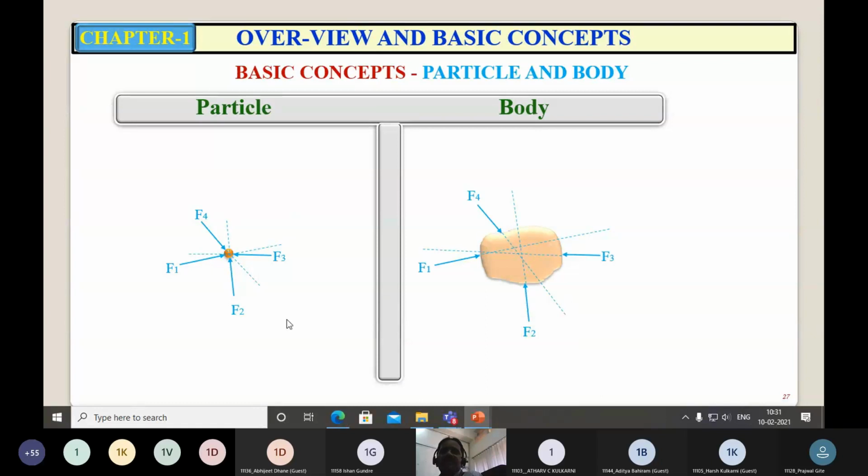So here, what will be the resultant of this force system? In the first case, it will have a resultant force, right? So it is a concurrent force system. So all these 4 forces will have a net force, nothing but the resultant force. And what is the resultant of the force system in the second case? Being that the lines of action are not passing through a common point, this force system will have a resultant which includes the resultant force and the resultant moment.